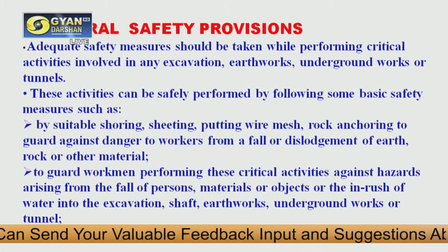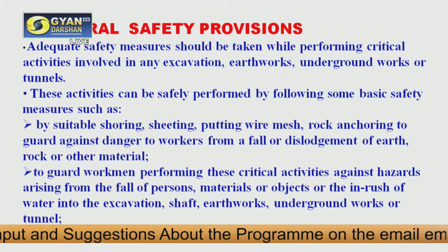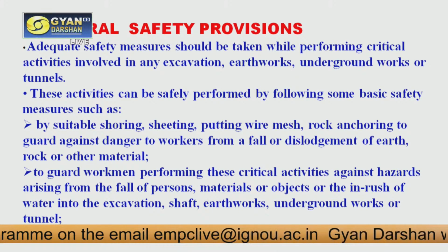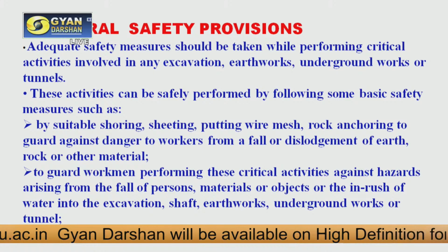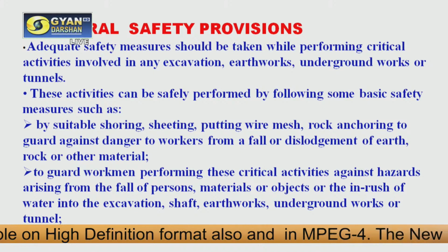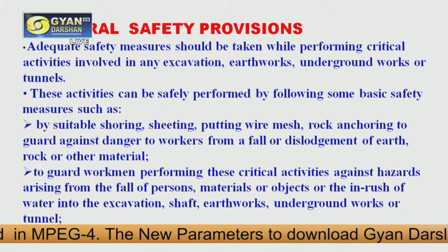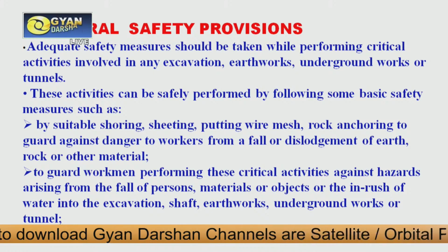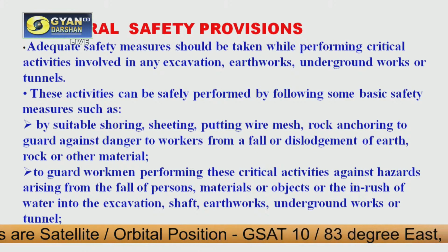Then there are certain general safety provisions, and if these are followed, then we can reduce the risk and the challenges in the underground work. What are these? Adequate safety measures should be taken while performing critical activities involved in any excavation, earthworks, underground works or tunnels. These activities can be safely performed by following some basic safety measures such as suitable shoring, sheeting, putting wire mesh, rock anchoring to guard against the danger to workers from a fall or dislodgement of earth, rock